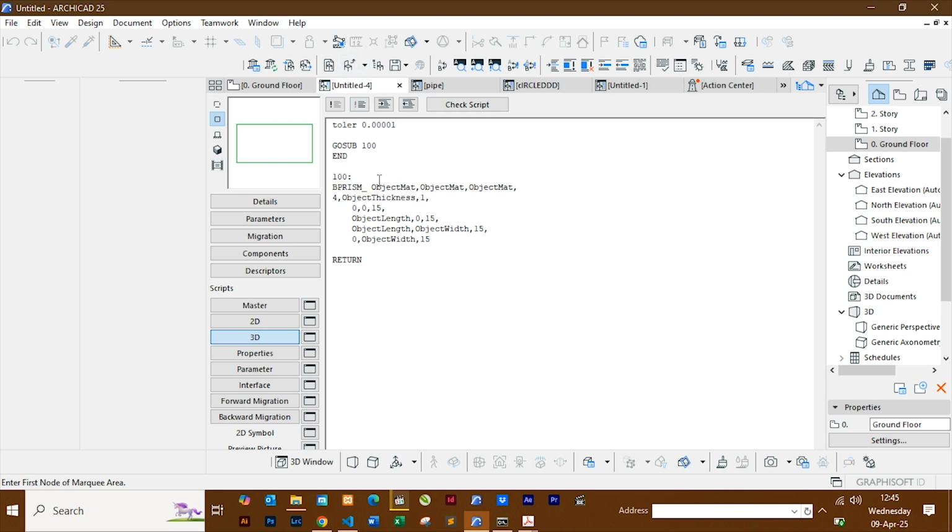For us to see, I need to rotate this thing first, and I'll rotate it in x, rotate x 90. And remember, we said for any transformation, you need to delete. We only have one transformation. So come here. Good. Now you are seeing this from the top.